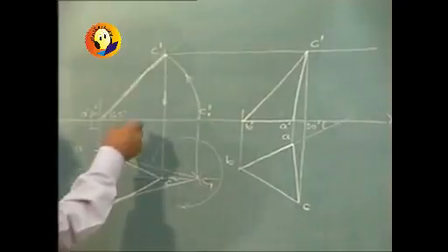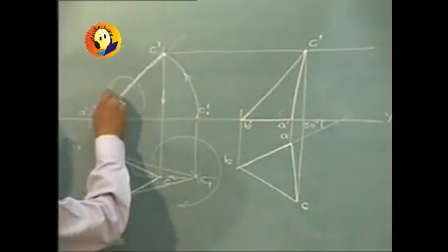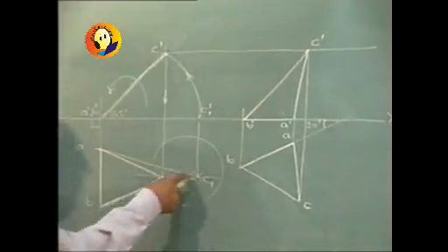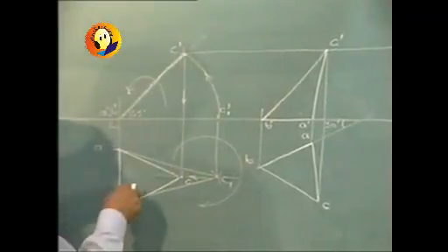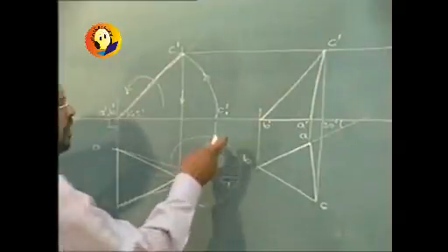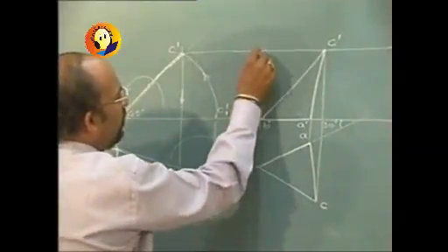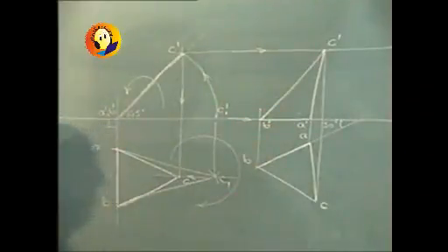So here we had one rotation in the elevation, movement parallel to XY in the other view, finalize plan, then rotate plan, movement parallel to XY in the elevation, finalize elevation, and so on. This is the procedure.